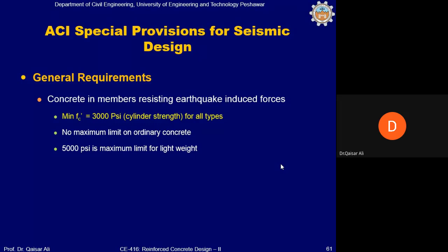So when you say that I am going to construct my building in zone 2B, and you want this frame to be SMRF, then you will take R factor as 8.5 and the base shear will be less. But when you do this in the beginning, because in the analysis stage we will decide whether I am going to design SMRF or IMRF, then at that stage the analysis parameter like R factor in the base shear will be considered, and the base shear will be calculated.